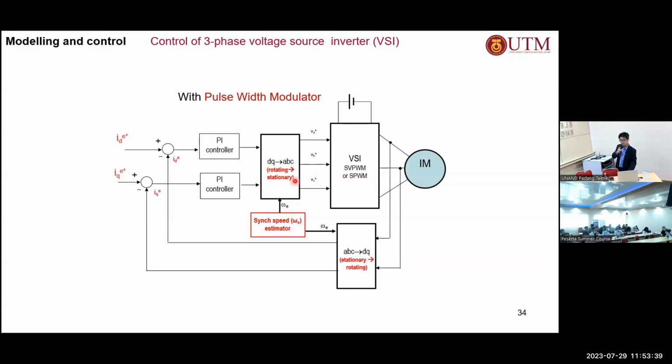Therefore, that is the reason why we have to have the ABC transformation as well as the frame transformation in order to implement the PI control. Now, research looks at implementing, instead of a PI controller, a fuzzy logic controller and other types of non-linear controllers.